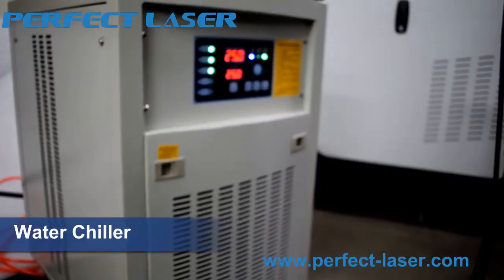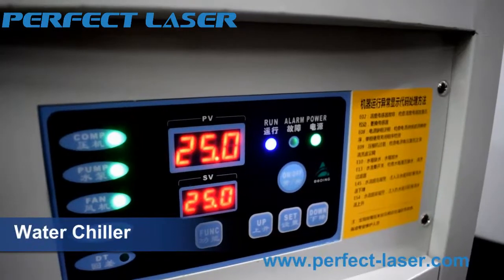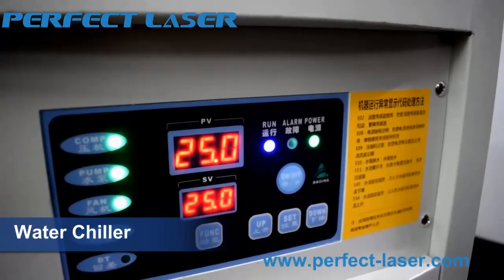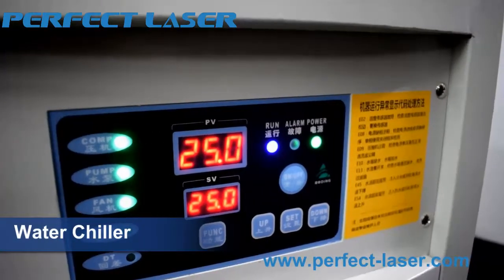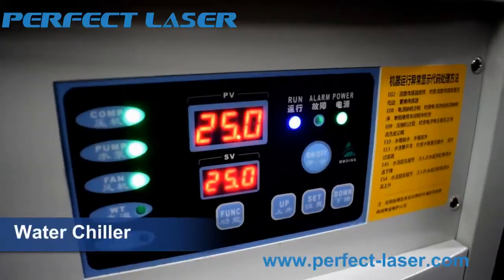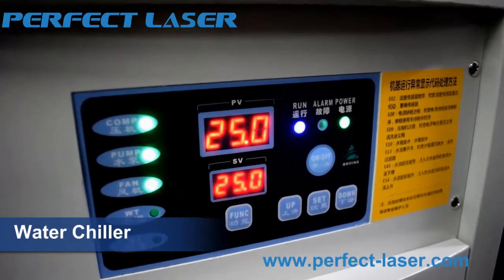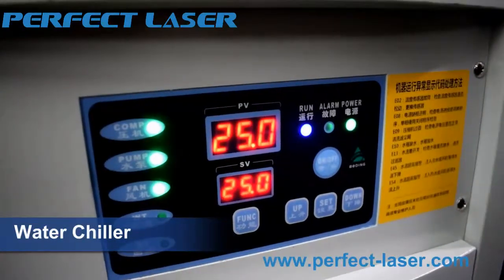the temperature of the water chiller. During the working of the machine, the water chiller temperature should be kept at 25 degrees. If the temperature is too high or too low, it will damage the laser source and the laser cutting head.